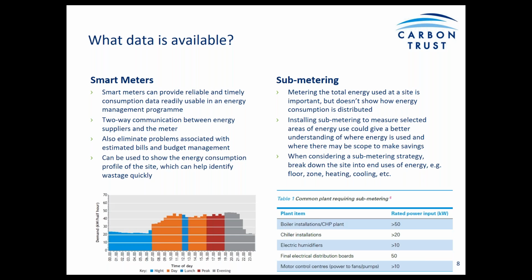And sub-metering of specific areas can provide more accurate energy billing, as mentioned, to tenants as well. If you have a site where you sublet to various tenants. A sub-metering strategy should also identify the individuals who are responsible for the energy consumption in those specific areas and ensure that they have the ability to monitor the consumption that falls under their management.